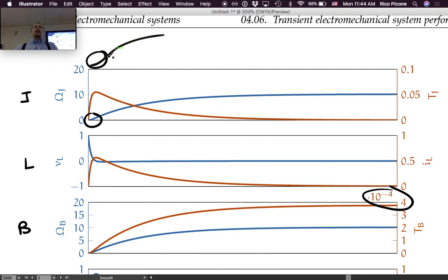So when we get this response data, we're just going to lop off what happens back here and ignore that, because tau 2 is still operating in that regime, so both decays are happening at once. And you can see approximately tau 2 operating in the torque. This is approximately how long it takes tau 2's response to finish, and then tau 1 takes over after that. So we're essentially just going to cut off this part and ignore this part of the data.